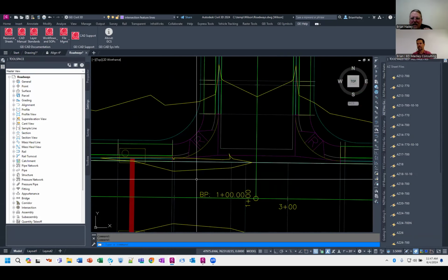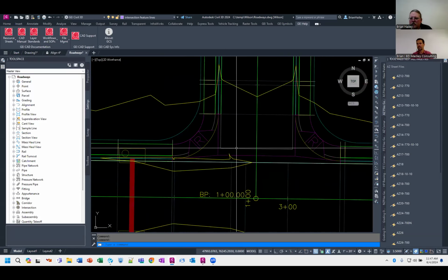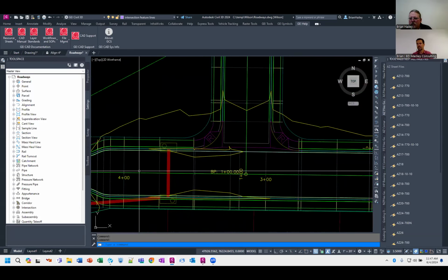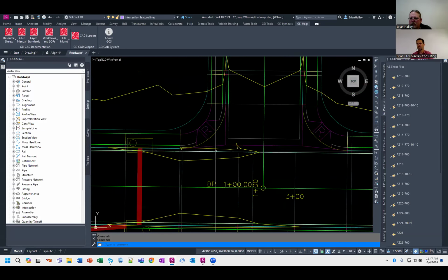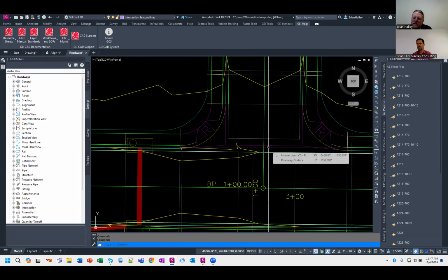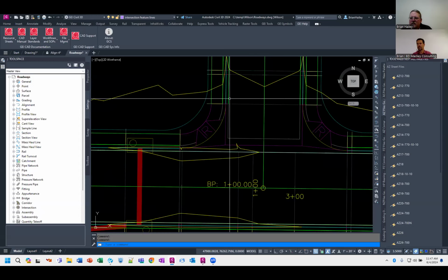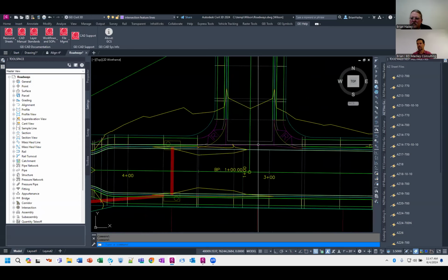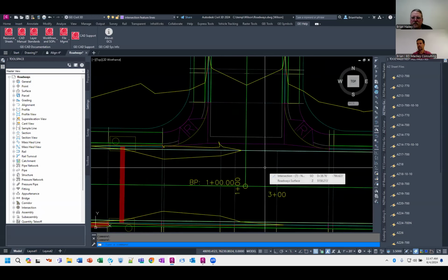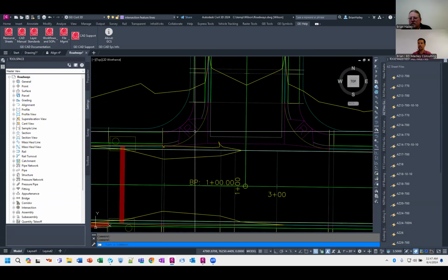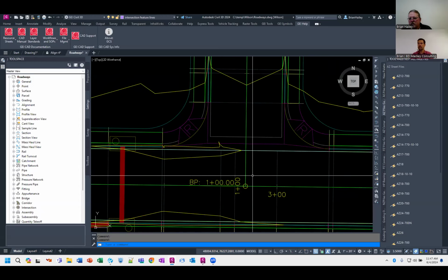In other parts of the world, they don't use crossbands very often, but we have a concrete pan at the intersection. The primary road is running through here, and then we have this pan for the water to go down the curb and gutter, and it's concrete, and it's wider, and it's narrower, it's flatter, and transitions. This makes an intersection a complex intersection. So I would not use the intersection tools in a situation like this.